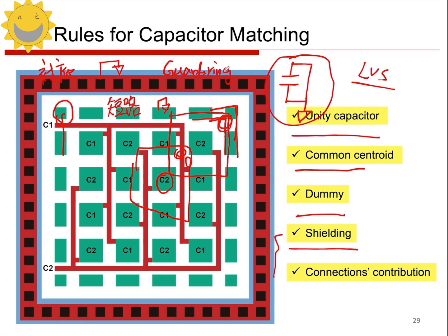We will introduce it in detail in the 5th lecture. The guard ring is a specific structure. How to use it? Let's draw a circle around this capacitor. This way we can shield the substrate underneath the capacitor. The purpose of this is to reduce the noise of the capacitor. Then the characteristics of the capacitor will be better, so it needs to be shielded.